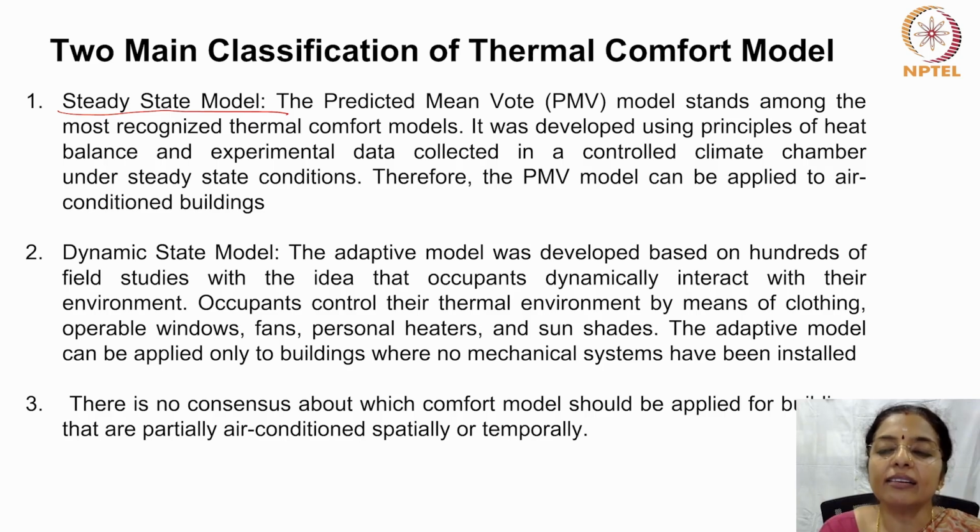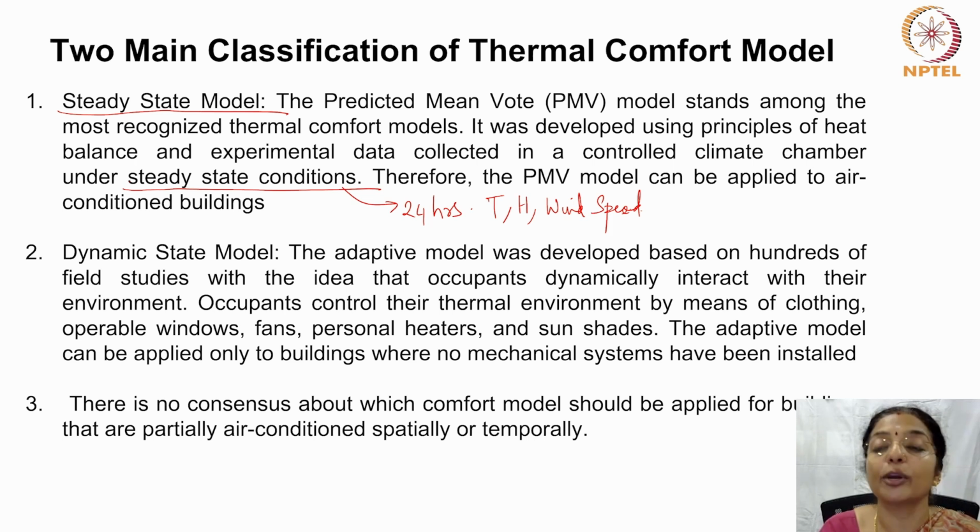So, under a steady state, what do you mean by under steady state? For say 24 hours, the temperature, humidity, wind speed, everything is fixed. And in that, people are assessed how they feel. But that is not the reality. In reality, the temperature indoors will not change only in air conditioned buildings because it is set so. Therefore, steady state model is applicable to air conditioned buildings.